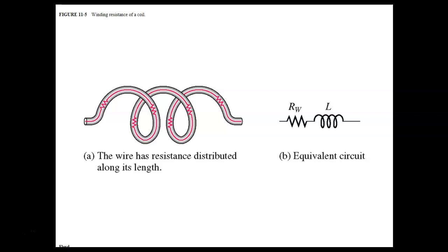And then we have to be really, really careful because you're depending on XL. Your stereo speakers are inductors, but they don't burn up because we don't put DC across them. If you put DC across that 8-ohm speaker, you're going to burn it up. They get their opposition from AC.